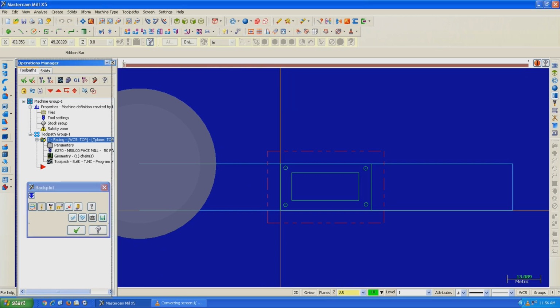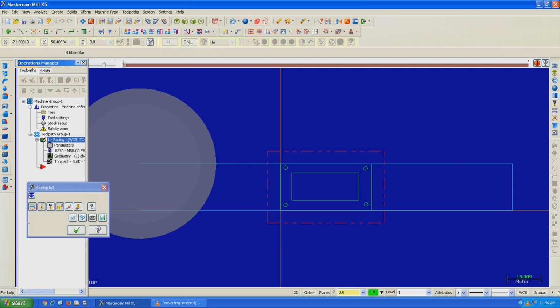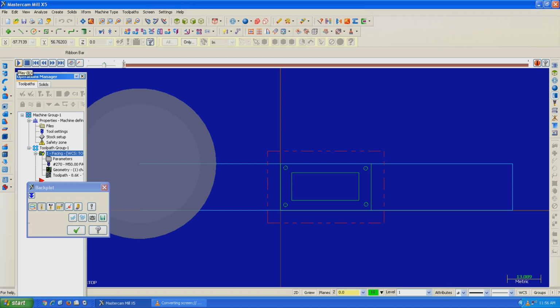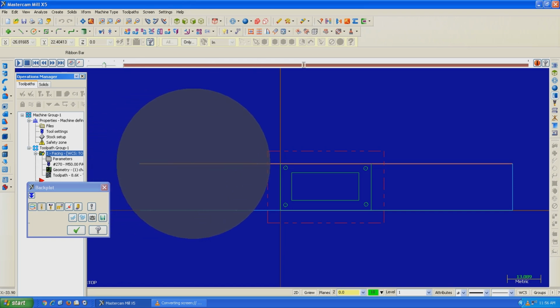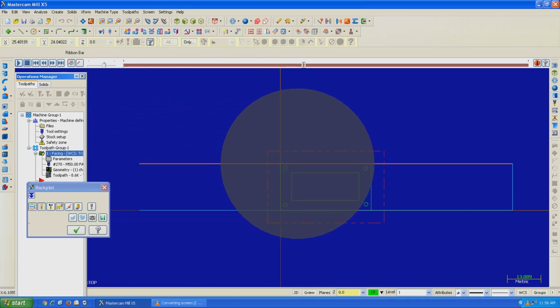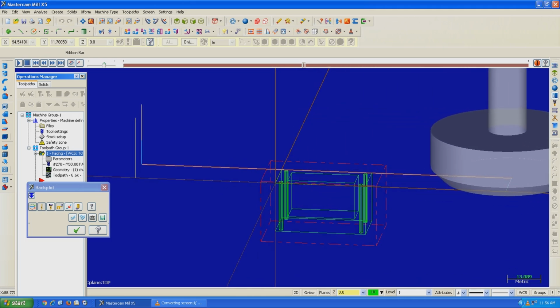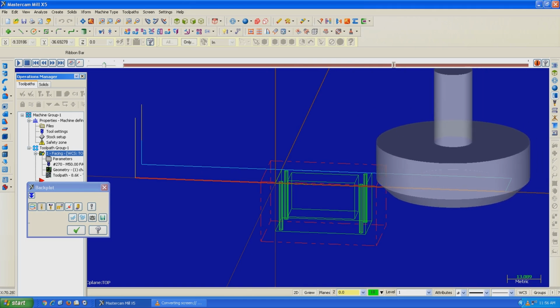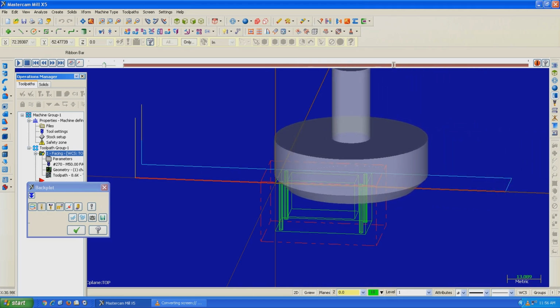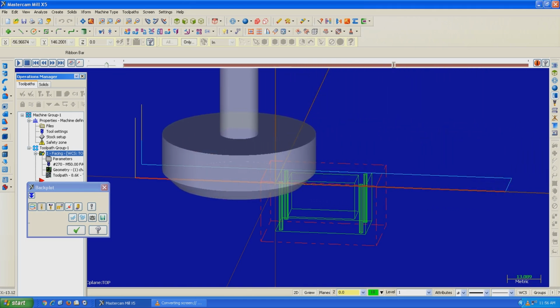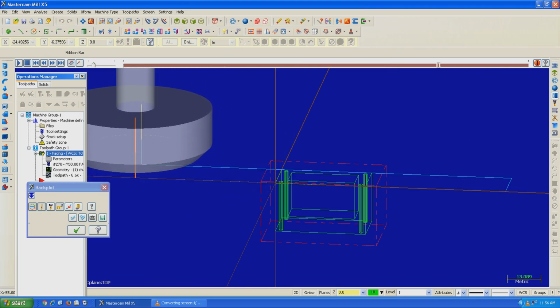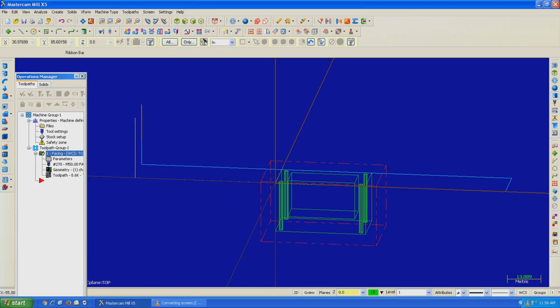So when we are in the back plot, let's see where the play button is. My play button for some reason is hiding. So I'm gonna lower this down. So right there is the play button. If I press play, yeah, it shows us the toolpath of the facing operation. It shows us exactly how the machine is gonna do this operation, and we can go faster or we can go slower. So this is the facing operation.